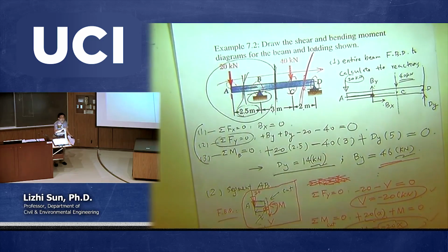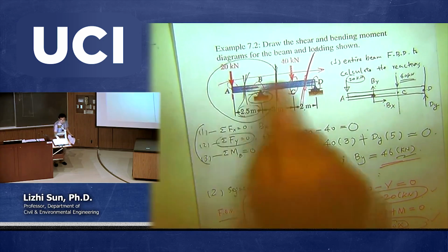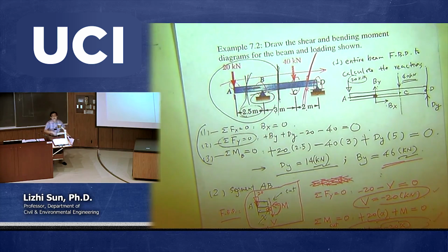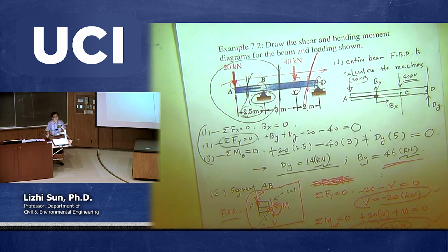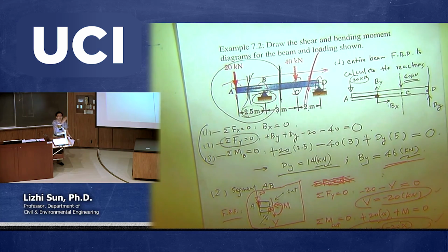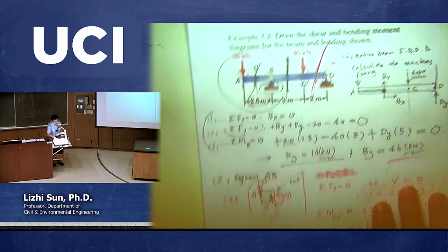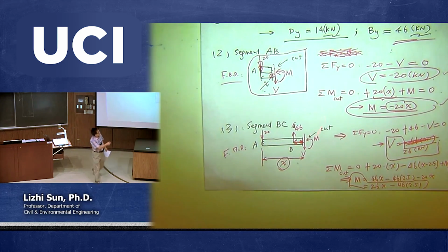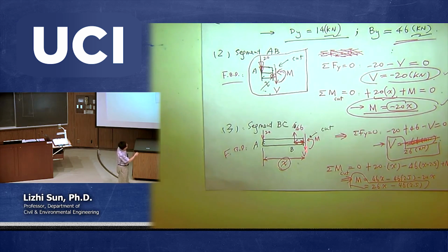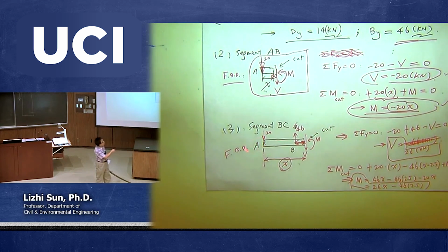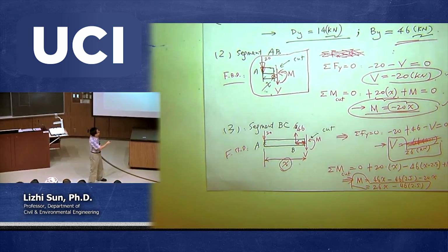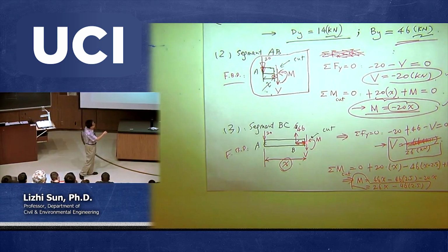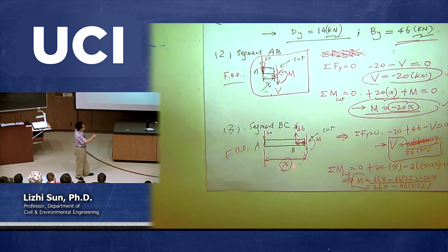Well, we went back. We are coming back to the original picture and making the cut. It's not that after we make the first cut, by sequence we're going to do the second cut. No, we come back to the original one to make another cut. Okay? Now we got the result based on the second cut, somewhere between B and C. When we make the cut, we're still starting from point A, the very left end. So then, we're going to call x the distance from the cutting point to the original point A.